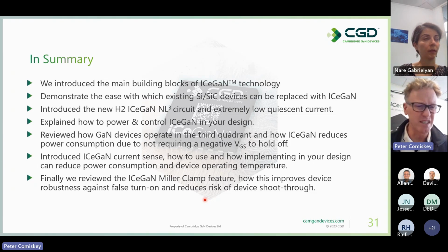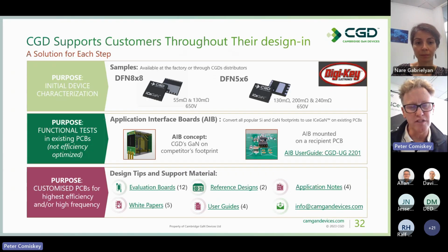Finally, we talked about the ICeGaN Miller clamp, and we just reviewed what the Miller clamp is, what that achieves, and demonstrated its value against false turn-on and ultimately avoiding device damage. I think in terms of the main content, that's pretty much what I wanted to cover today.